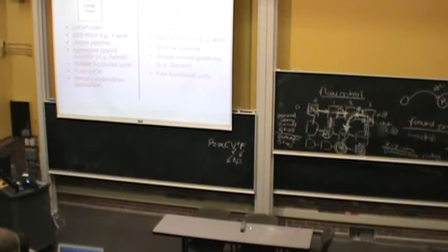So let's take a look at what these small and large cores are. This is just an example. A large core, I'll call large, what that means is powerful. It could be out-of-order, it could have wide fetch, deep pipeline, aggressive branch prediction, all of the things we've discussed, multiple functional units, memory dependence speculation, what happens with loads and stores. We did not discuss trace cache, but this is one way of supplying many instructions in a single cycle to a wide machine. A small core can be in order, can be one wide, can have a shallow pipeline, 2 stages, 3 stages. Can have a simple branch predictor or no branch predictor. Can have few functional units.